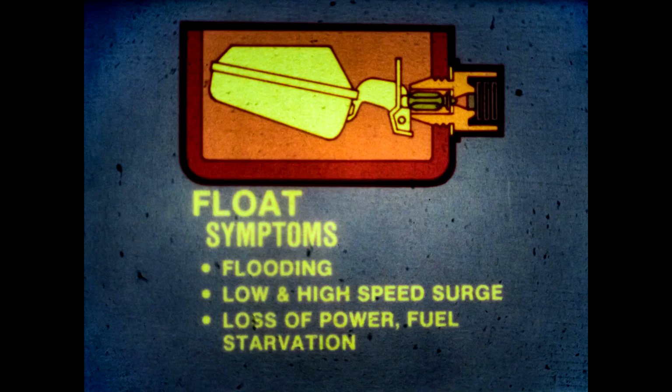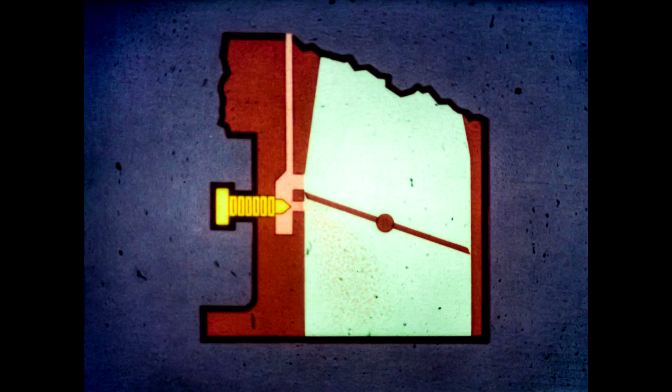The float affects drivability. Some typical float-related drivability symptoms are flooding, high or low speed surge, loss of power, fuel starvation. Literally any symptom, whether at idle, low speed, cruise, high speed acceleration, or full throttle operation, especially during turns, can be caused by an improper float setting.